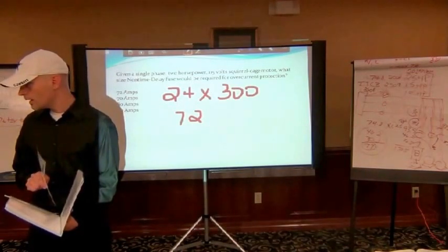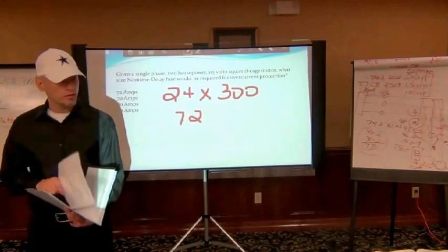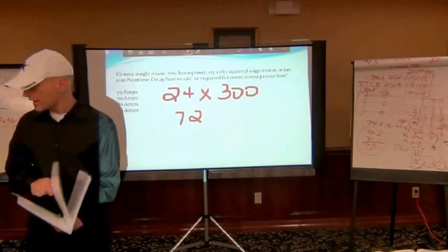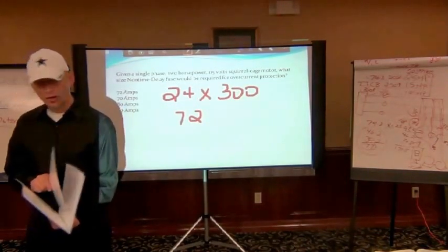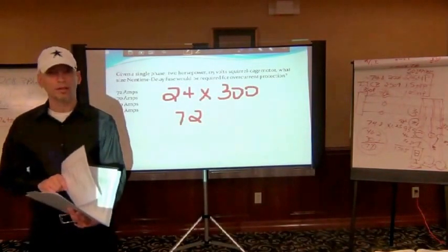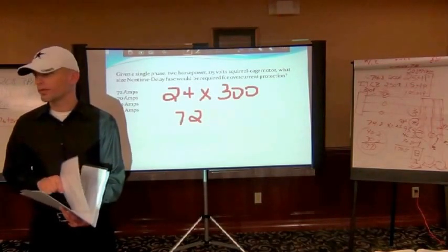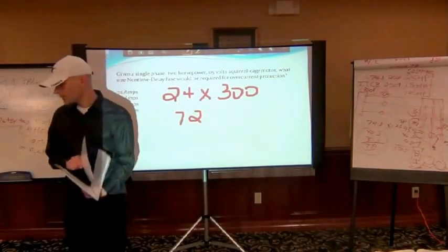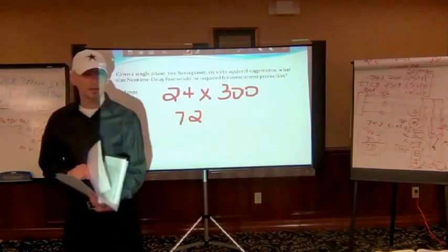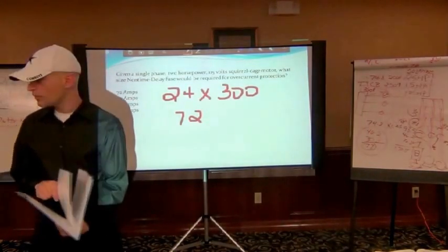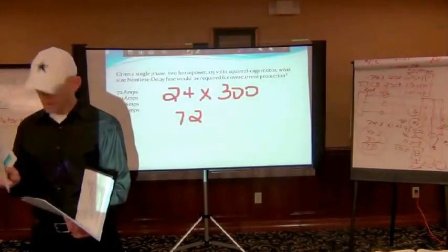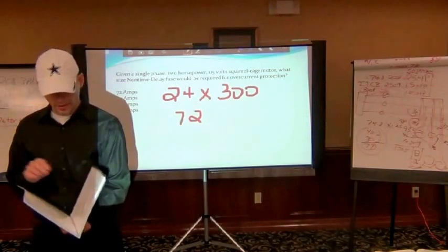Now the service factor 1.15 with no trouble starting, what number would you use for that? Exception 1. No, that's not right. I'm sorry, did y'all say page 323? No, that's wrong table. Talking about heaters, overloads, right? Sorry, I jumped too quick at page number because I had too many people say the same thing. That's not a good thing. 319, right? No trouble starting means that you're in the standard setting. Page 319, that's going to be, for a service factor 1.15, what value? 125%, and then round up or down? Down, exactly.